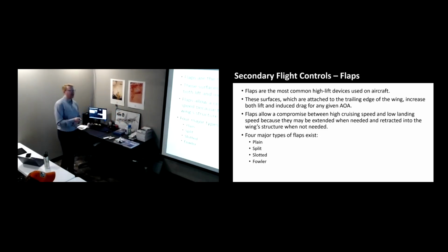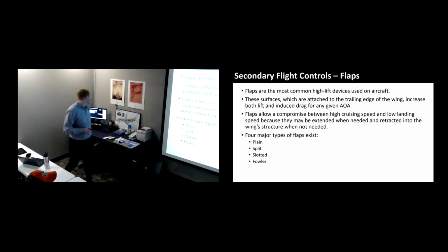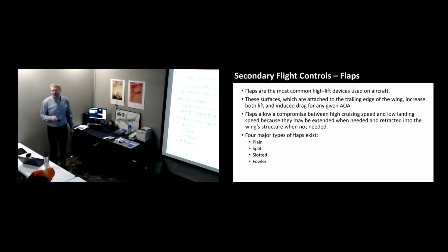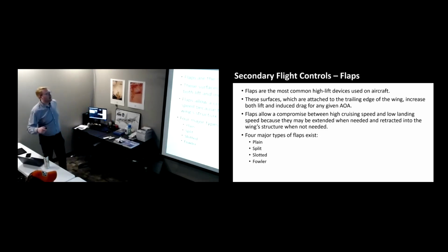Trailing edge of the wing is where we include these flaps. You can probably assume high lift device means it produces a lot of lift. I'm not going to get into the aerodynamics too much immediately, but I'll at least give you a moment to think about this. When the trailing edge of the wing falls, where an aileron is coming down, it's starting to have a higher angle of attack and produce more lift. That's what the flaps are going to do over another portion of the wing.